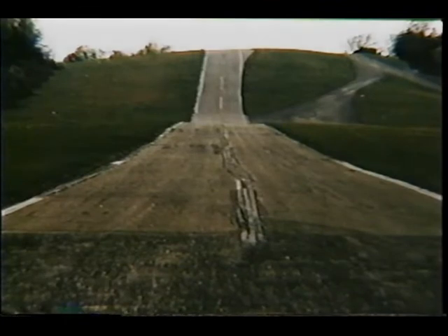Runway slope can be a real factor, though, if the airport you're landing at has not been built to government standards. So a word to the wise, get as much information as possible about destination airports before flying there. If you do land on an inclined runway, the rule of thumb is to always land uphill, wind and obstacles permitting. But check Unicom first, and always announce your intentions.